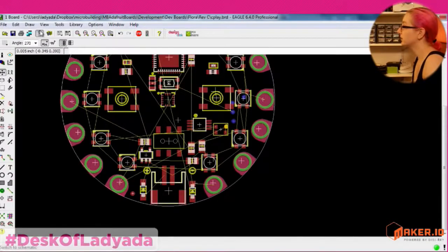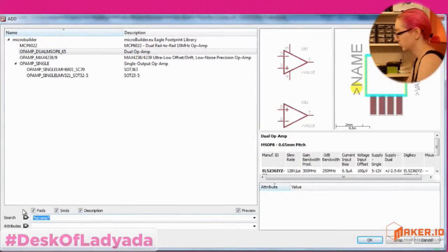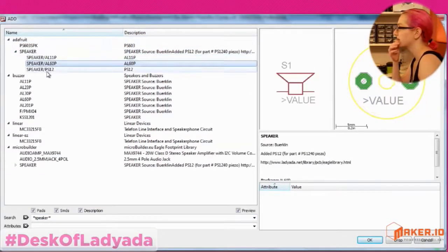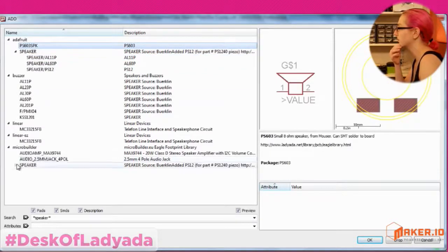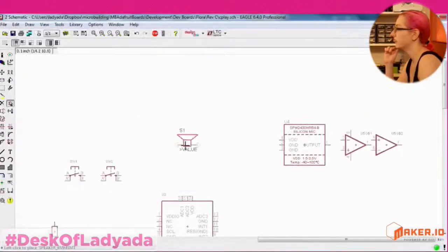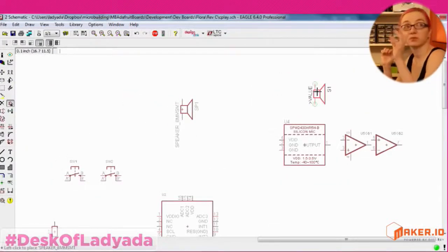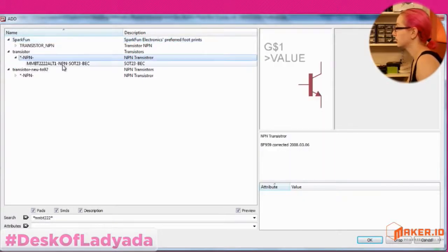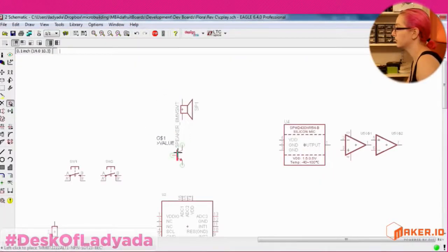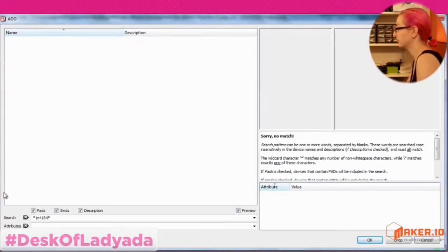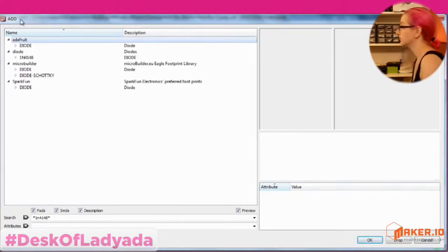And then over here we're going to put a speaker. In the first version, I ended up going with not one of these through-hole piezos. I ended up going with an 8mm buzzer. There's a little speaker coil inside. And then, of course, you'll need a transistor. One of these will do the job quite nicely. And then, of course, you need a diode as well, because it is a speaker. It's a coil. It's like a little inductor.